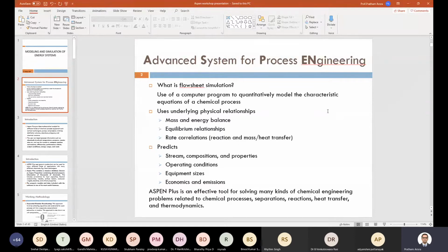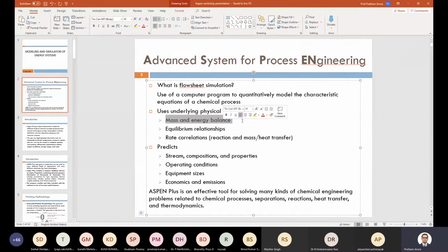Most of the processes that you would encounter in any bioenergy system would be chemical in nature. There would be a group of compounds reacting to form another group of compounds. Simple chemical equations. So the things that you need to incorporate or estimate would majorly be mass and energy balance. What is the mass of the different chemicals, compounds, elements going in, and what is coming out? What is the energy associated with that reaction? Is it an endothermic or an exothermic reaction? Do I need to supply heat, or would heat be produced in this particular reaction?